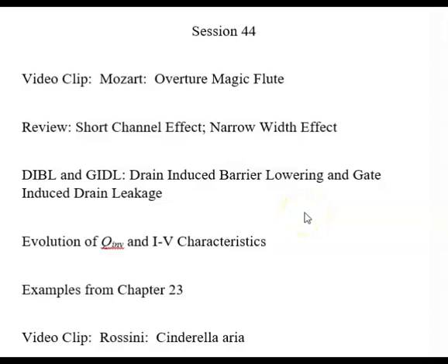Welcome back, and here are a few of the topics we'll be covering in today's session. We're going to start with the short channel effect. By short channel, I mean a short L. And we covered that a little bit toward the end of last session. When the L goes down, the threshold voltage goes down, and the gate loses control over what happens in the inversion process. Not so good.